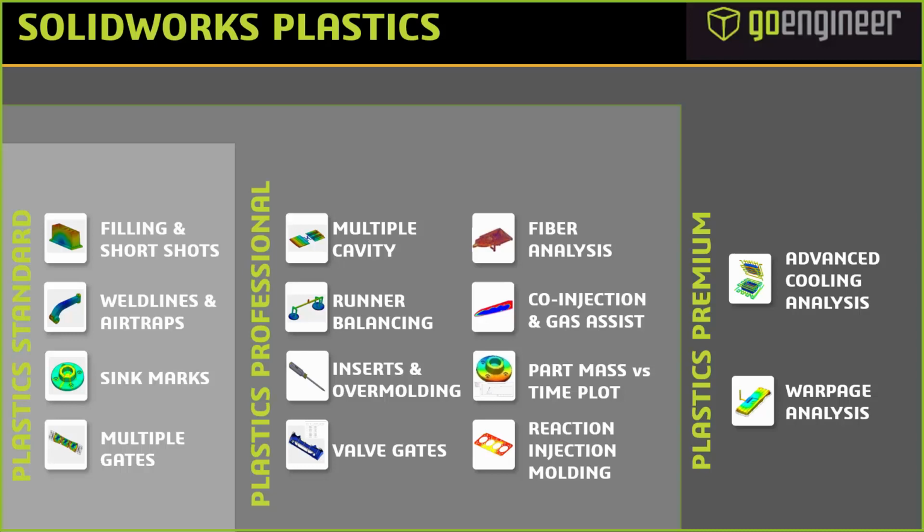So that's where SOLIDWORKS Plastics comes in. I've got the SOLIDWORKS Plastics simulation software. Plastics comes in 3 levels. Plastics Standard was created more geared toward a part designer. For this simple little bug part, that's kind of where I'm standing, because all I want to do is see if it's going to fill or if it's going to short shot.